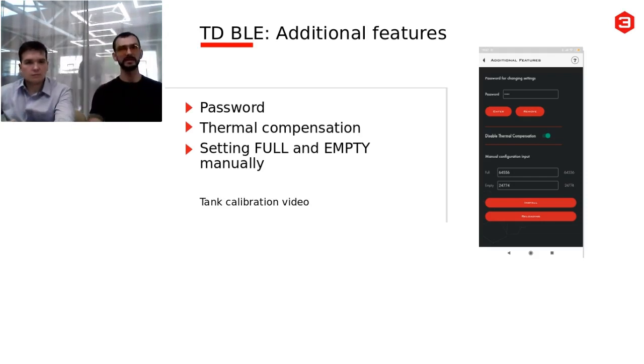To predict that, we have installed temperature sensors inside the head of our sensors that can, by the use of a thermal compensation algorithm, predict that shrink or expansion. So when you fill up the fuel tanker inside a warm garage and then drive out into the cold, you don't see that somebody stole 800 liters of your fuel, but instead thermal compensation helps you avoid that kind of false readings.